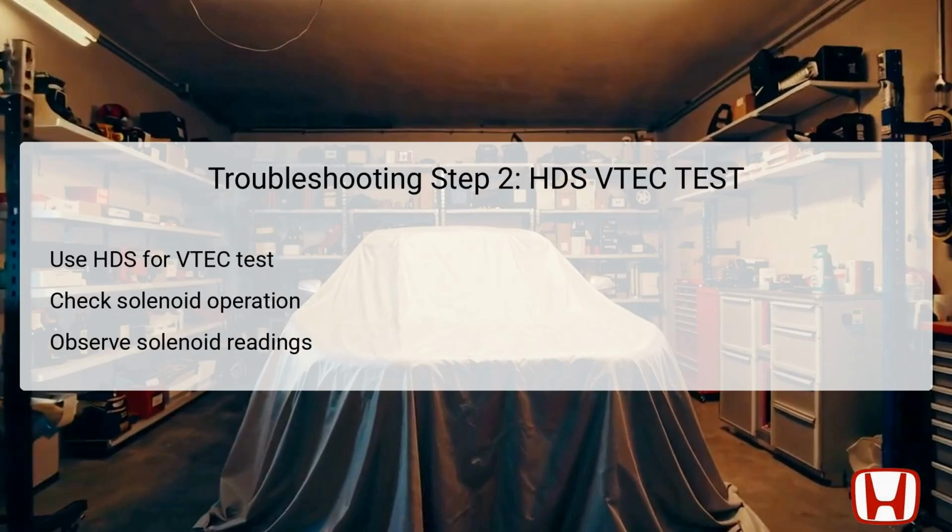The second troubleshooting step involves utilizing the Honda Diagnostic System, HDS, to perform the VTEC test. VTEC, which stands for Variable Valve Timing and Lift Electronic Control, is crucial for adjusting valve timing in response to engine conditions. During this test, technicians need to check the operation of the rocker arm oil control solenoid to ensure it responds properly to PCM commands. Problems detected here may indicate issues with either the solenoid or its associated wiring.